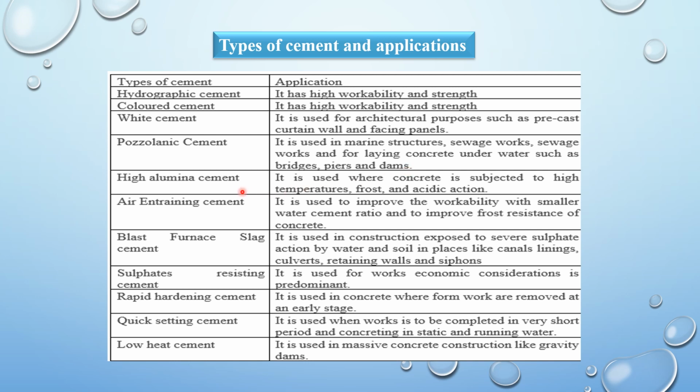And the next cement is high alumina cement. It is used where the concrete is subjected to high temperature, frost and the acidic conditions. Students, the construction where the acidic exposure is more, then we use the high alumina cement.